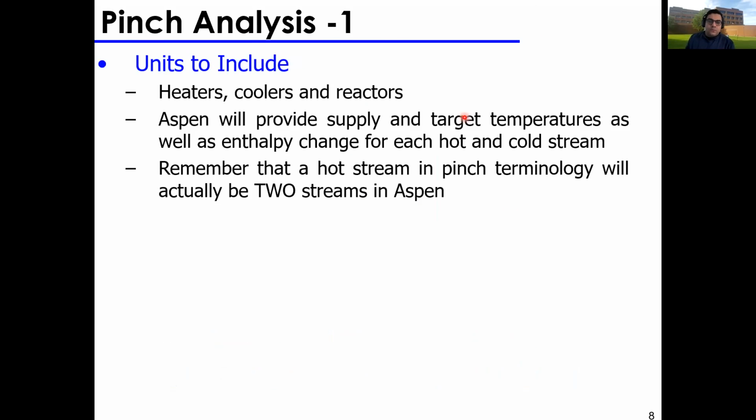Okay, so another thing you want to consider at the early stage of design is doing a pinch analysis. Okay, and you need to do a high-level pinch analysis. The idea of doing a pinch analysis is not to close in on the final design, but to get an understanding of potential reductions in utilities. Okay, and when doing pinch analysis, you need to consider three things: your heaters, your coolers, and reactors, i.e. your heat exchangers and your reactors, and nothing else.